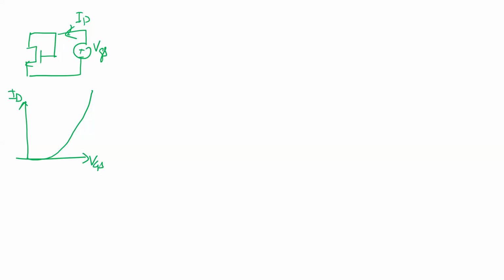And that's what we did yesterday, where you took a diode and we linearized it by doing a Taylor expansion. Then we dropped everything from the square, cube, and fourth order terms. We just kept the linear term, and then we did some calculation of, okay, to what value of the input, how large or how small is the input, for which this model is valid. Okay. Now, what did I say yesterday? So you do a small signal model. How small a signal does it have to be for the model to be valid? You remember we discussed that yesterday?